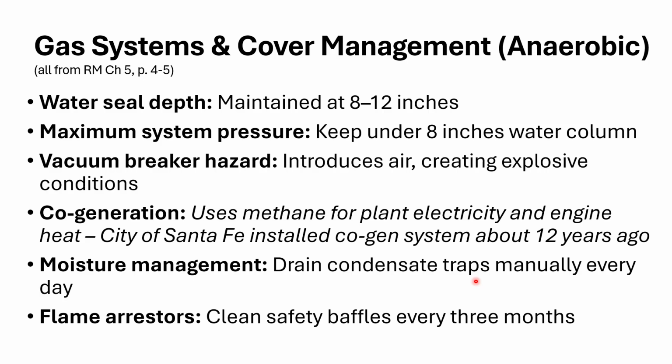If that doesn't happen and you allow that condensate to build up, you're kind of defeating the whole point of gathering that methane, because you're going to have moist or water mixed with that methane, water vapor mixed with the methane. It's not going to burn very well in a generator or in a flame arrestor.